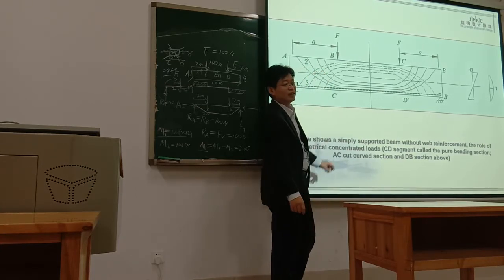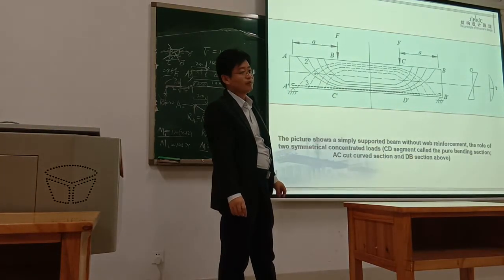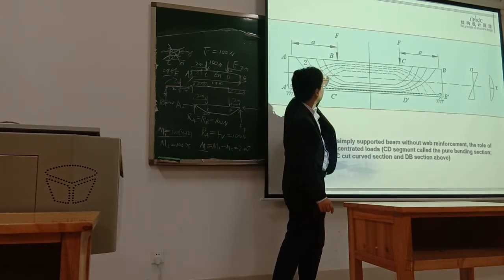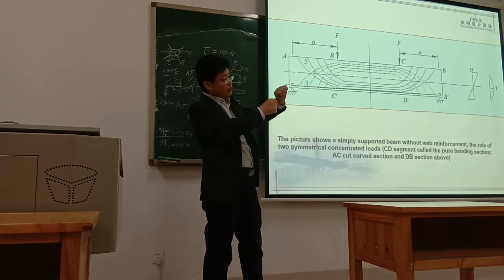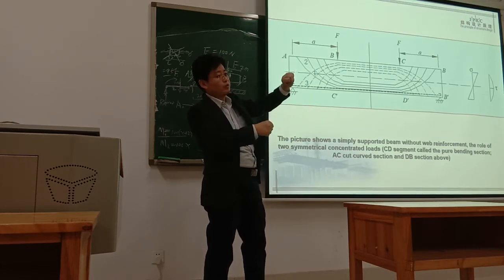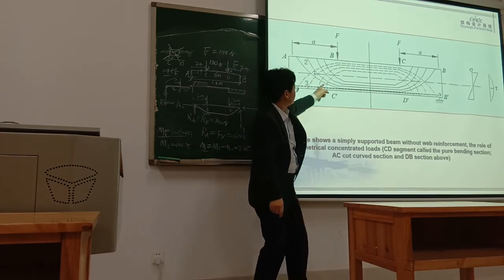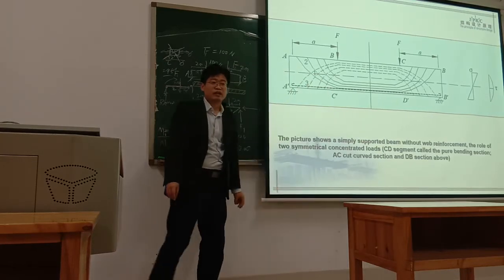So if you pull it, the crack will be from like A prime to B. When the crack is generated, it will be from A prime, the down part, to that, from this point to this point, this direction. Yeah, because you see, the crack is normally perpendicular to your pulling stress. If you pull this direction, the crack is this direction. So this line is the tensile force, so the crack is normally in this direction. Compression too.